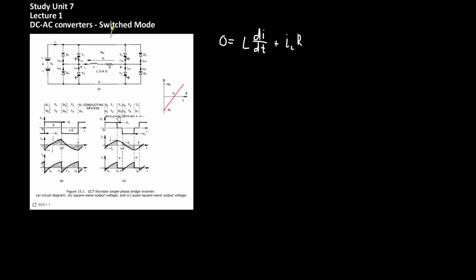It should be noted that there are multiple zero voltage loops in this circuit, so there is not necessarily a reliance on this T1 D3 loop to generate the zero voltage, but there's also a T3 D1 loop, which will also generate a zero voltage. And these zero voltage loops will be alternated throughout the cycle, and this is to reduce stresses on the actual semiconductors.